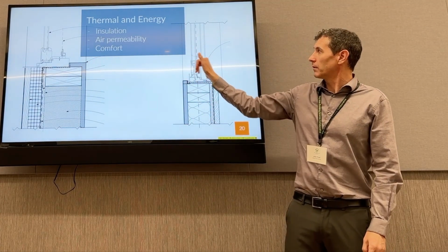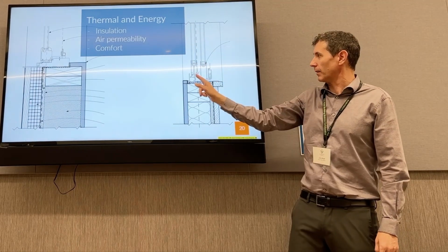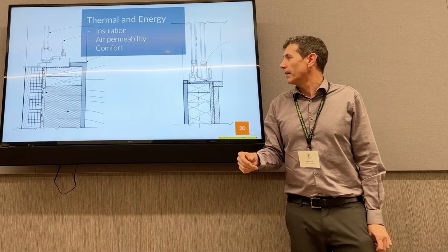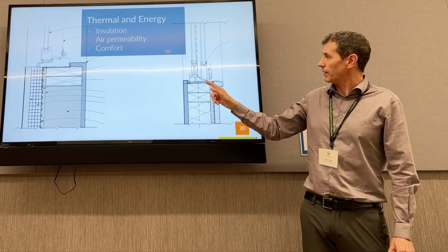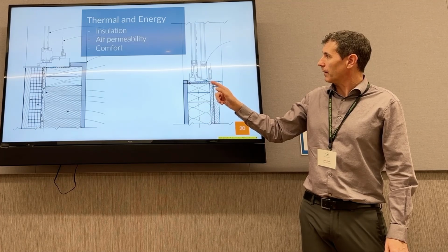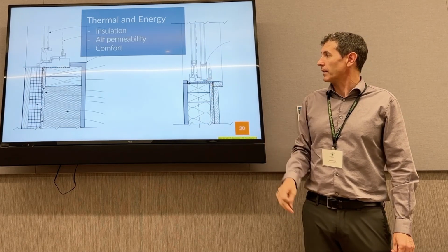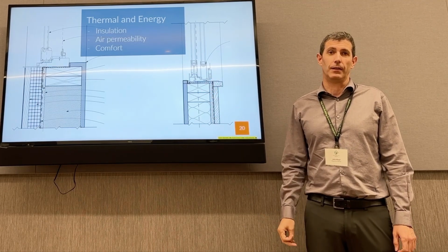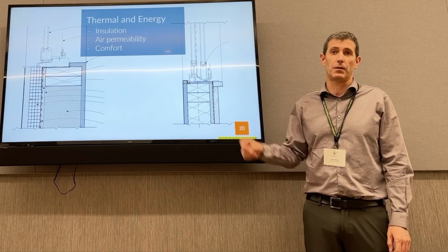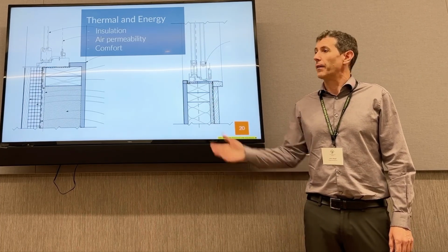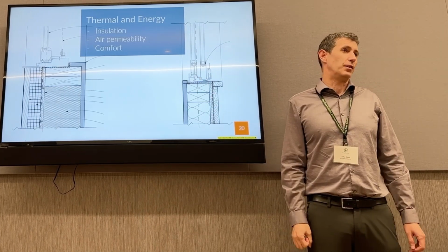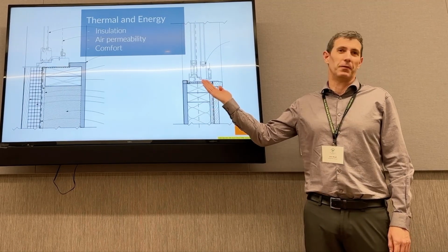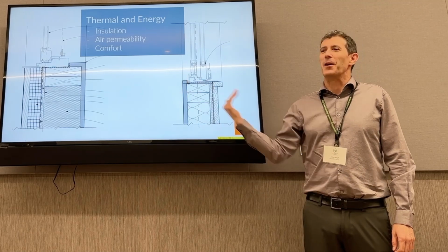These are new double pane. In this case it's a sliding gliding window, double pane glass. In this case, it's not even a thermal break for the sliding window. It wasn't required to pass the Title 24 requirements, and they wanted a sliding window, so they got this. There are, of course, plenty of options that are thermally broken that are much better, and that's what we almost always use. But you're seeing the worst one for comparison's sake.